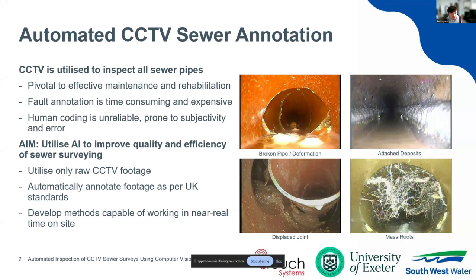maintenance or rehabilitation. So whenever anything happens in the pipe, whether we're called out to a blockage or we're doing major civil works, CCTV surveys are done before and after every time we touch those pipes. So first off to check what's going on, and then afterwards to check that we haven't broken anything else and everything is fixed as it should be.